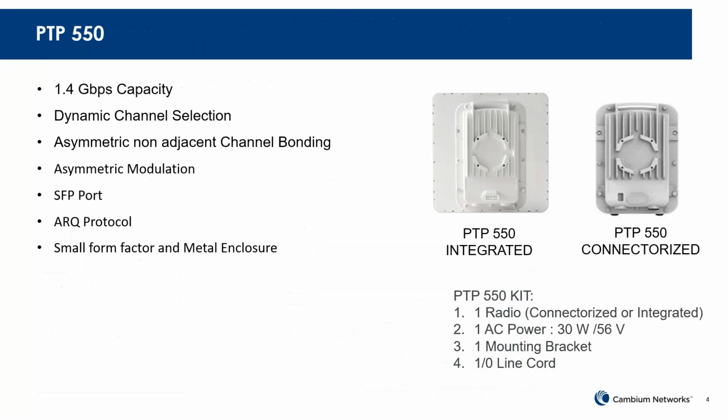So 550 is not a single radio with one channel, because as we said earlier, 5 gigahertz as a whole is unlicensed, and there is a lot of interference. If you have a super wide channel, say 80 meg or 100 meg or 150 megahertz, then some interference will be covered in that channel because you can't find a really clean channel that wide.